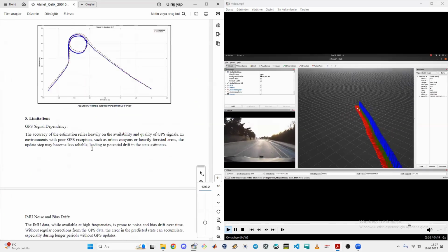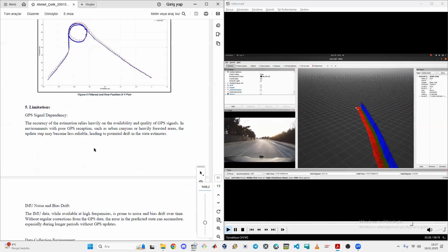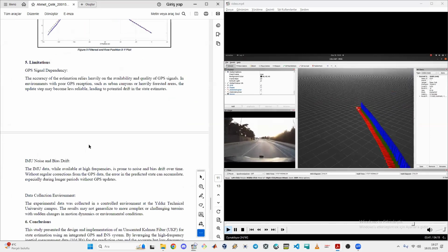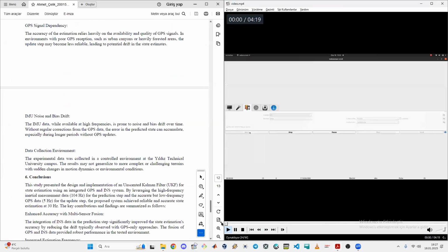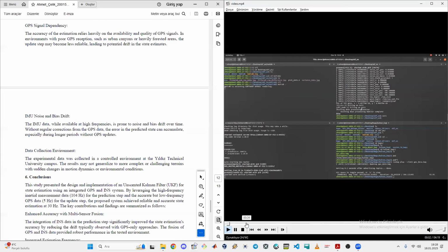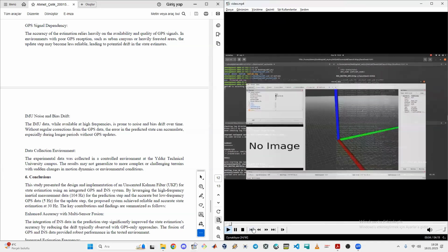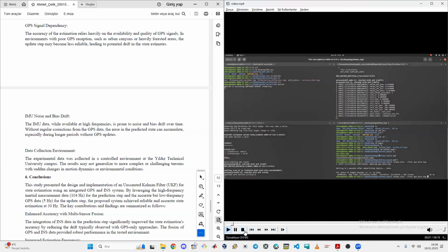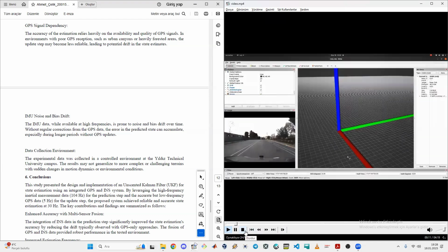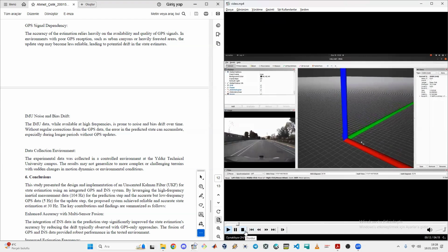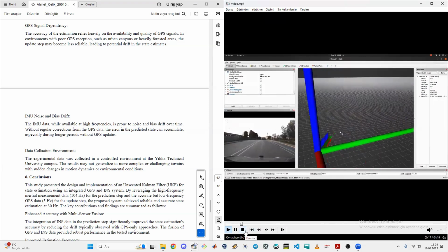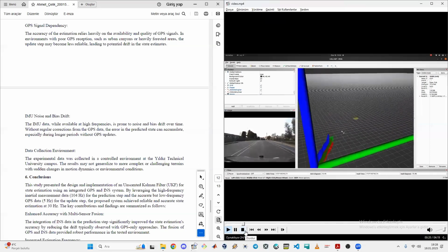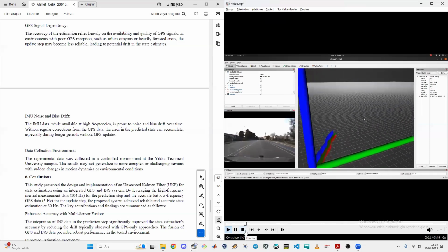And limitations. Dependency on GPS signals. The accuracy of the state estimation is highly dependent on the availability and quality of GPS signals. In areas with poor GPS reception, such as densely built urban environments or heavily wooded regions, the reliability of the update state decreases, which can result in drift in the estimated states.